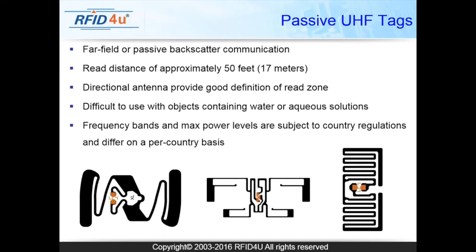It's a directional antenna, so it's putting out a beam that you can focus in one direction, as opposed to HF where you had a spherical magnetic field. It's difficult to use with objects containing water or aqueous solutions. Once again, UHF is absorbed by water. And the frequency bands and max power levels are subject to country regulation and differ on a country to country basis.